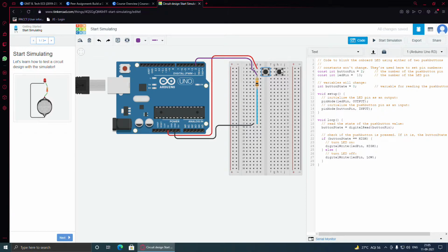Okay, so we know Ohm's law. Ohm's law is basically V is proportional to I, or the potential difference across two ends of a conductor or an electronic component is proportional to the current flowing through that component or conductor. So it means that if the potential difference, or the voltage across the two ends, is increased, the current will increase. In the components that we use in IoT devices, the voltage remains constant. In some cases it's 5 volt, in some cases it's 12 volt. So if the voltage remains constant, the current rating will also be constant, because it is characteristic of the device or component that we are using.